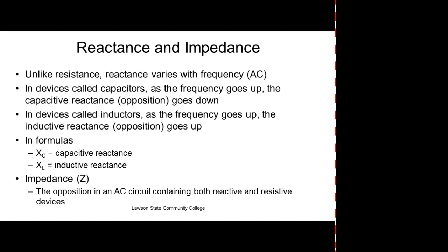It filters out what you don't want to get through it, right? So in power supplies, we're going from AC, which is a varying garbage, over to something that's got to be steady. Well, we're going to have to filter this stuff out. So we use filters, and they're either going to be inductive filters or capacitive. But these are going to work in a DC circuit. So when we get into power supplies, we're going to look at primarily capacitive filters. And that's going to take a chopped up AC waveform and convert it into a DC form.